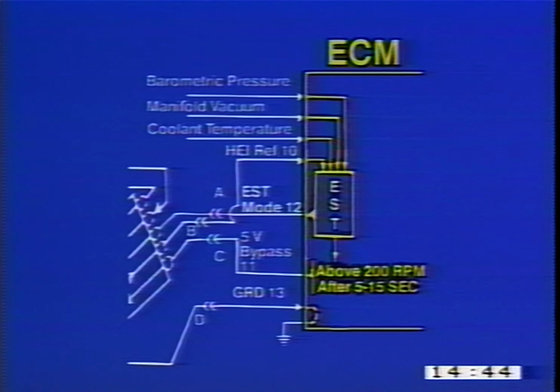When the engine is started, the ECM is ready to supply the necessary spark advance for optimum engine operation. The spark advance signal is based on incoming sensor and ECM pre-programmed data. This electronic spark timing signal is a duplication of the original HEI reference signal, with the exception that it has either been advanced or retarded as needed by the ECM.